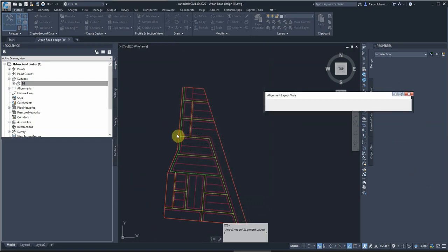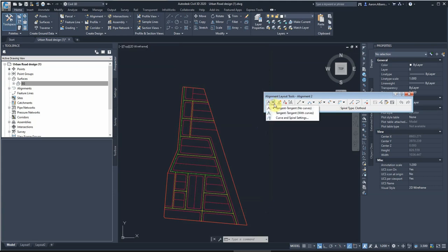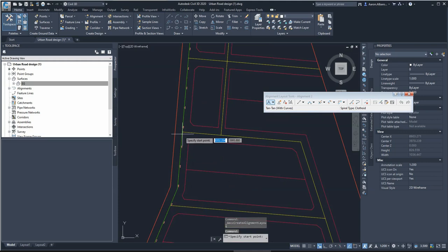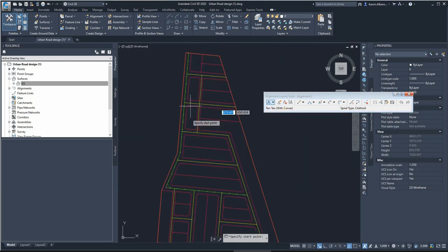All the same specification as we agreed. Please keep an eye on the direction. You will see later on the direction is important to us, so we know to create the correct cross sections and components that we will need. So I chose for alignment 1 north, traveling all the way south. I'll choose the same for alignment 2 from north to south. There's no rule about it as long as you know where you started and where you ended. Usually I try to start either north or west, so top or left. Okay, so it's up to you.